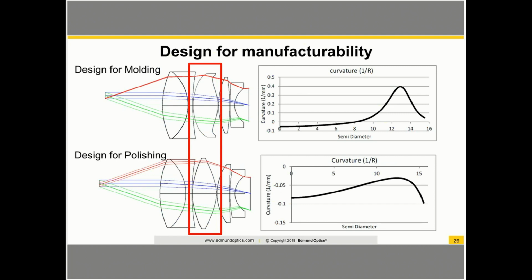However, one thing that needs to be kept in mind here, we have to make sure that this lens remains moldable. What is moldable? There are two things that need to be taken into account, the thickness of such a lens and the ratio of diameter to the central thickness or the thickest part of the lens, as they have to be kept under a certain limit. On the other hand, one should try to avoid making an Asphere that is expected to be ground and polished from having too complex of a shape. Complex shapes for ground and polished Aspheres result in a longer and more complex manufacturing process that inadvertently results in higher prices.